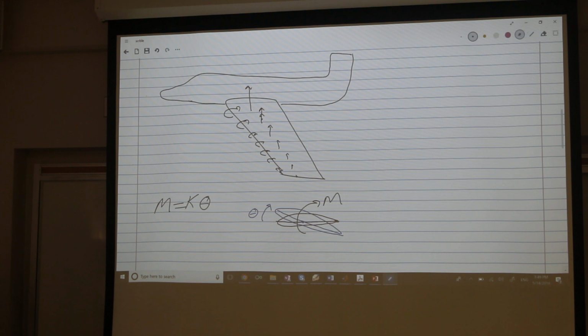Yes, Leo? But in flight, don't you just trim the airplane so there's no Cm, where Cm equals 0? Cm equals 0 where? What is the condition for trim? Cm equals 0 where? At the CG. So at any other point there is a moment.